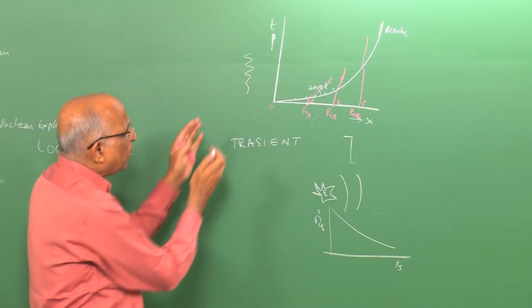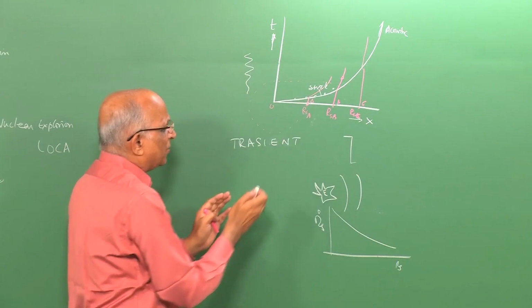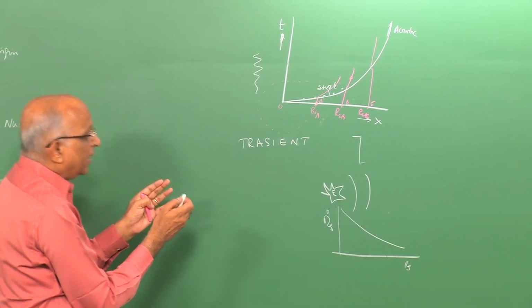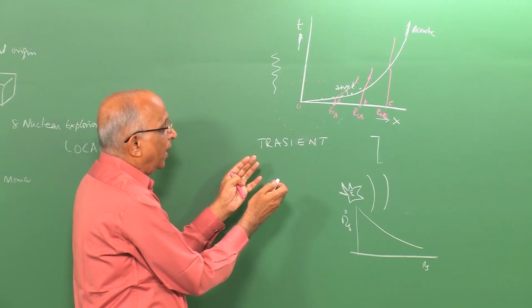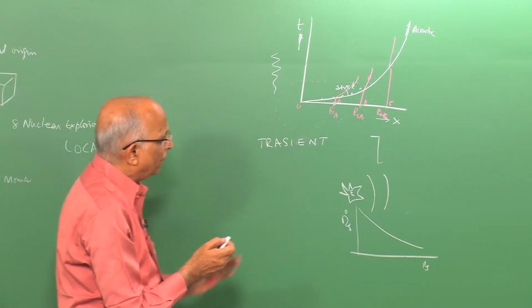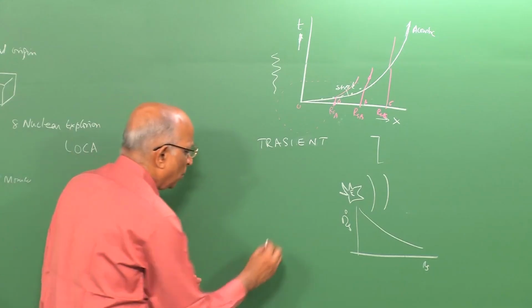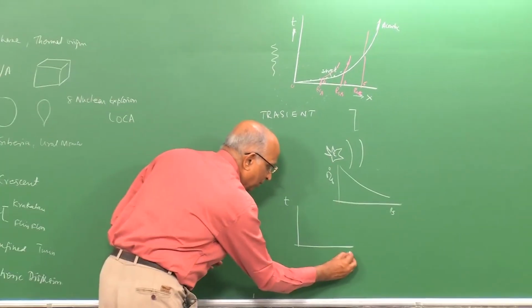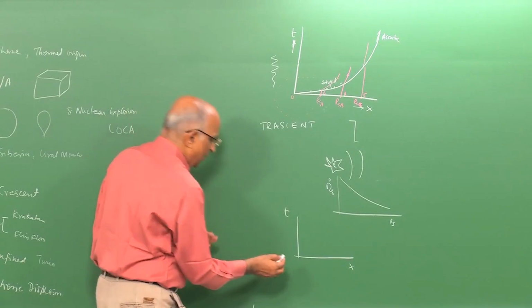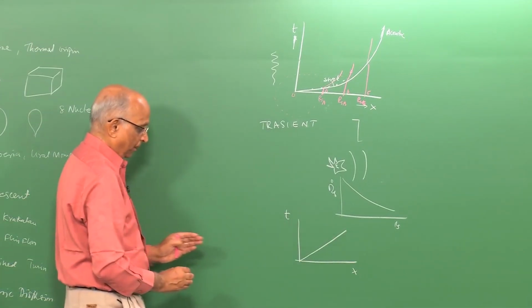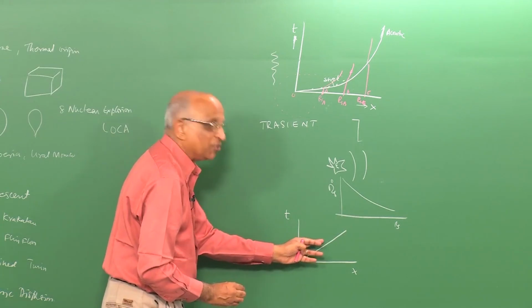But before I get into some detailed predictions, can we make the problem a little simpler, understand the problem a little better, and how do we do that? Instead of looking at the decaying shock wave, can I look at the properties on the streak diagram, t versus x? Now, I say, if the shock were to move at constant velocity, can I predict the properties behind it?